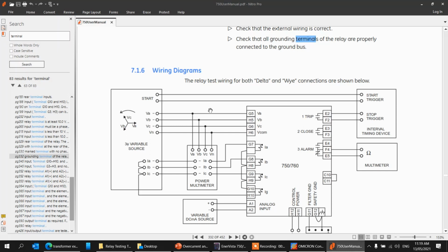In this scenario, another trick is you can do this as a wet contact, dry contact, as long as you remove one leg of the wire. Exactly. Because the principle of wet contact is a loop going back to supply.